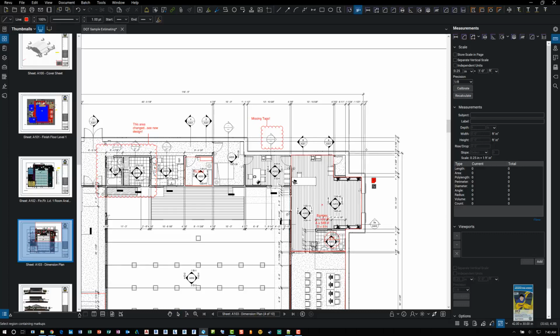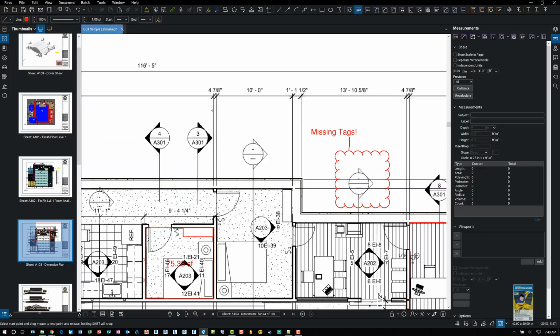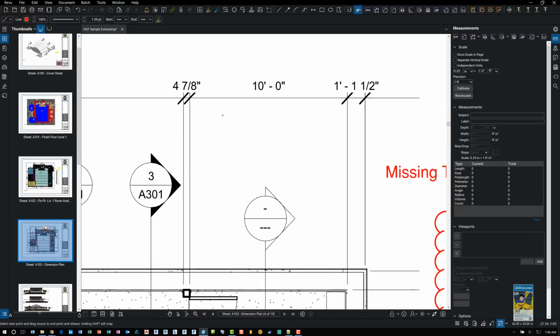You'll get a window that tells you to pick 2 points to measure, so we'll click OK. And what you'll do is you'll pick something that makes logical sense. For example, here this says 10 feet. Make sure your snap to content is turned on so that you can see and it can snap to that data. You can see how it gives you the little nodes like that.